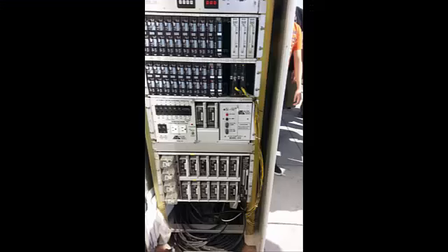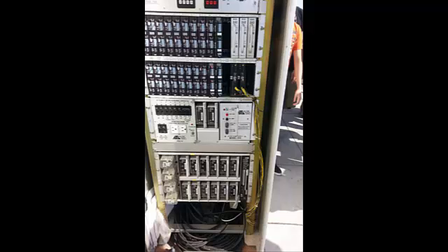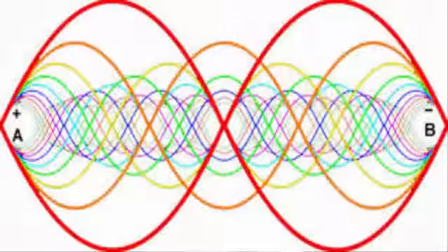Detector units are referred to as detector amplifiers when they are used with inductance loops. In addition to identifying vehicle actuations, the detector amplifiers also power the inductance loops, resonating them at a selected frequency.